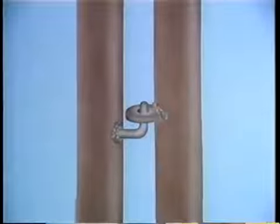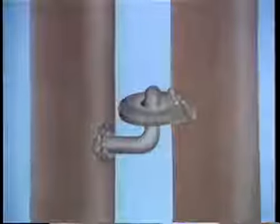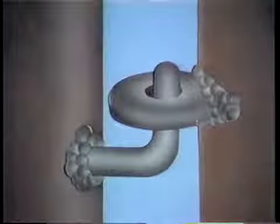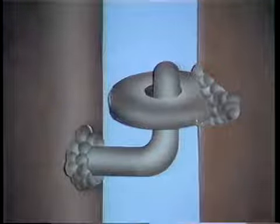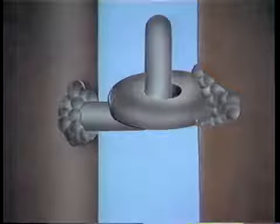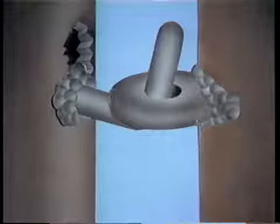Tearing of tube metal at support clip attachments is also caused by expansion and contraction. Support clips are brackets that are welded to some tubes to help hold them in place. If tubes that are held together by support clips expand or contract unevenly, a tube may be torn open where the clip is welded to the tube.